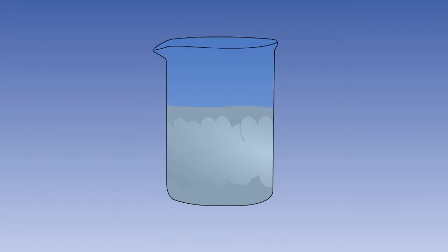If a fuel sample is placed in a clear glass container and swirled vigorously, and the sample appears cloudy or hazy, then there could be one of two reasons for this. If the cloudiness appears to rise quite rapidly towards the top of the sample, then air is present. But if the cloud falls quite slowly towards the bottom of the sample, then water is present in the fuel. Having said that, a cloudy appearance usually indicates the presence of water.